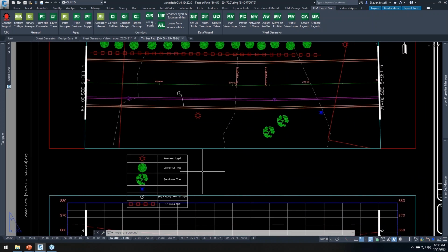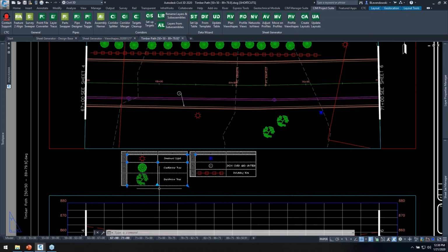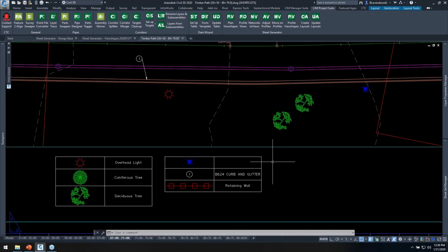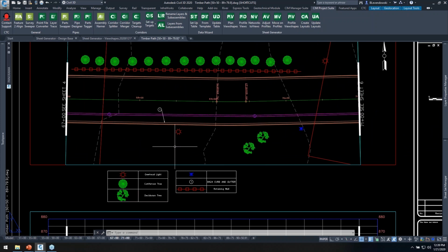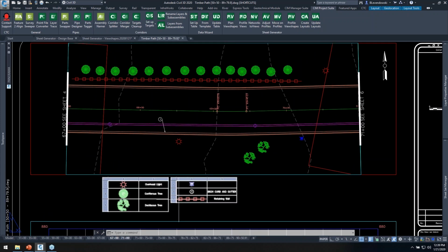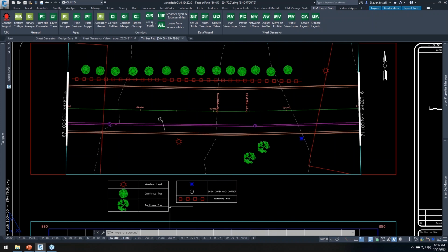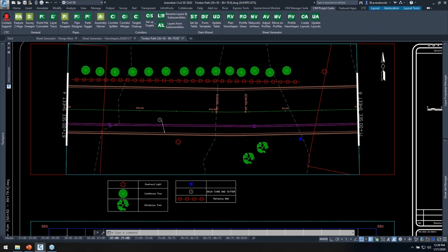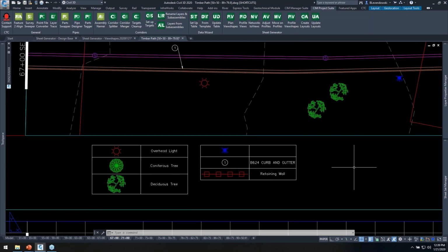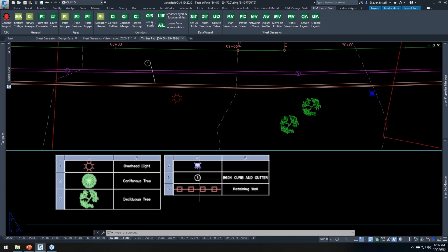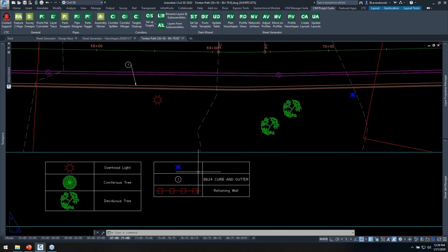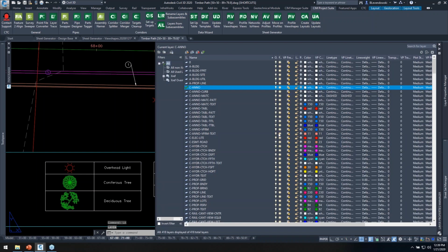Okay. Now it's a simple table, but it's just what was in our sheet itself. Okay, it's an AutoCAD table. It's just a native object, so nothing proprietary. But you'll notice it's scaling it to the scale of the objects in the sheet itself. Okay, it's grabbing a line sample there. And it's reading this data, this description. I chose layer description, but you could be pulling it from layer name. You could pull it from attributes in the multi-leader block, any number of things. And here, this hydrant, for example, it didn't pull anything through. So I just kind of want to highlight how this works.